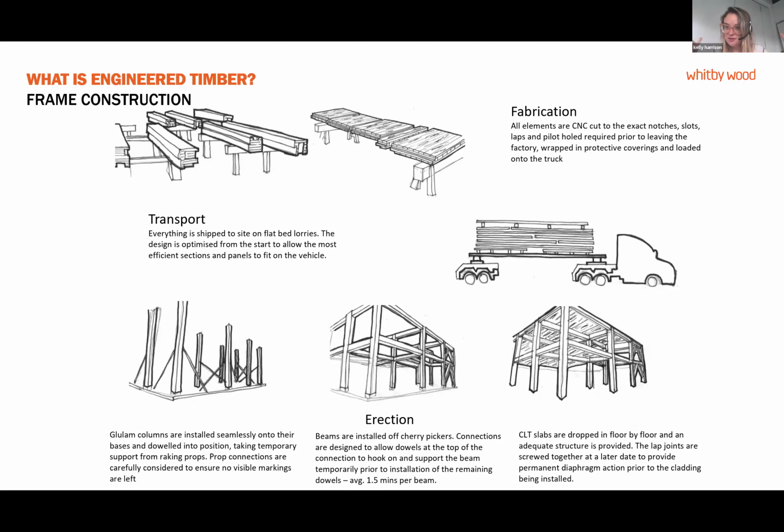And you've normally got a nice flatbed lorry. A flatbed lorry is probably about 13 meters long. So normally we try and keep your members to a 13 meter maximum length. I think that's also the same length as a shipping container if it has to go overseas as well. And so 13 meters is where you want to keep it, unless you've got to pay lots more for a special transport of some sort.